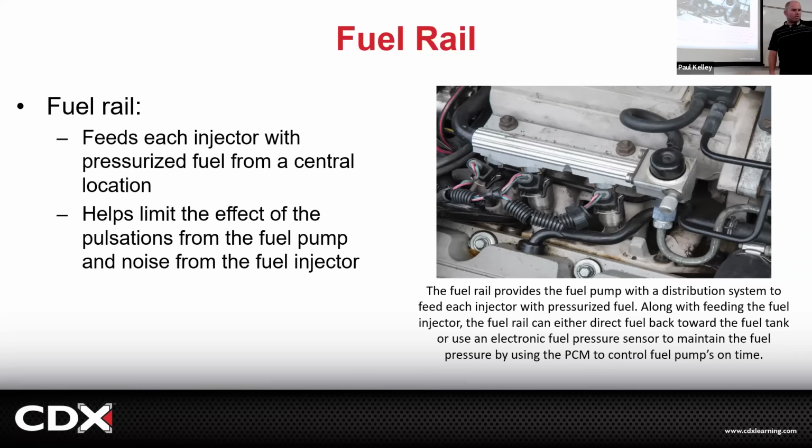But if we need to do an injector, the injector is stuck between the engine, probably the intake manifold, and the fuel rail. The fuel rail pushes it down. There's an O-ring here and an O-ring down here. This O-ring seals the intake port from outside air. So if this lower O-ring failed, it would be sucking air in past the O-ring. That's going to throw off our fuel trim numbers, stuff we cover next time. What do you think if it was the upper O-ring where the injector seats into the rail? What if that upper O-ring was messed up? It'd leak what? Okay, and that's scary.